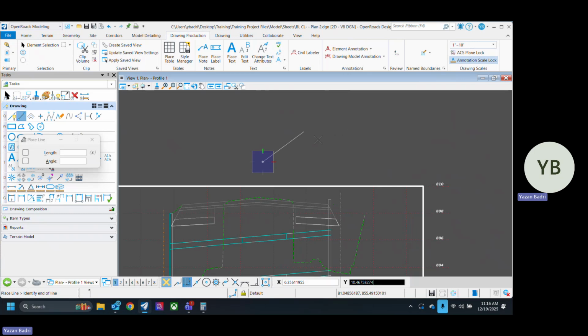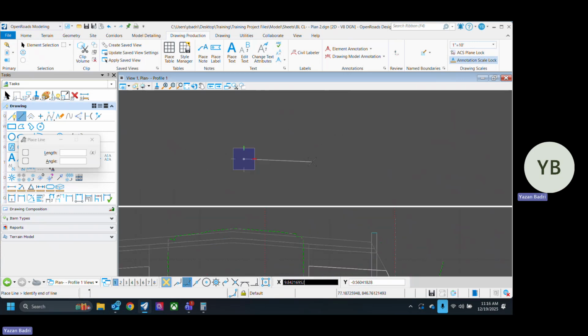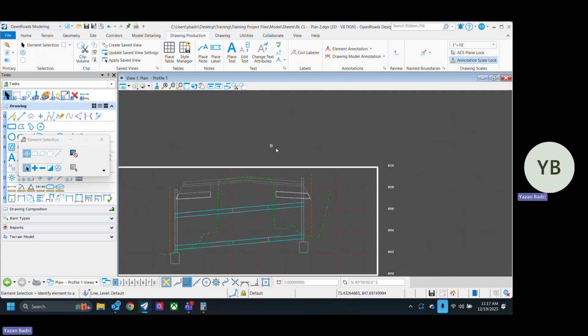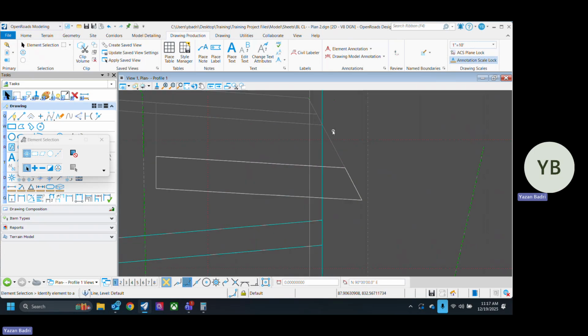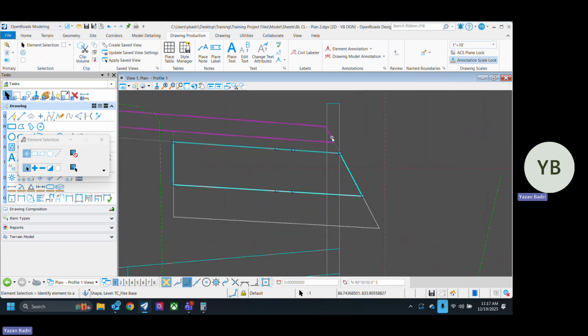Or if you're trying to draw a line, right? Yeah. This gives you an X and Y lock. Or say you want to draw the line at a certain angle. You just click M and it changes it to polar coordinates. See at the bottom? So instead of drawing a line, then rotating, you can just hit tab and do an 80-degree line, for example. So it just helps you draw stuff more accurately. Especially with this, right? The pavement stuff.